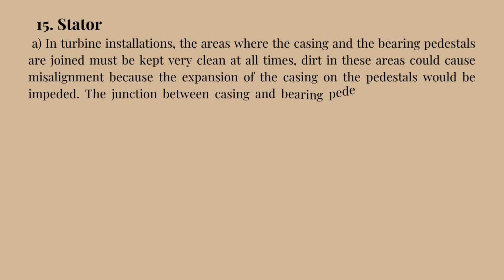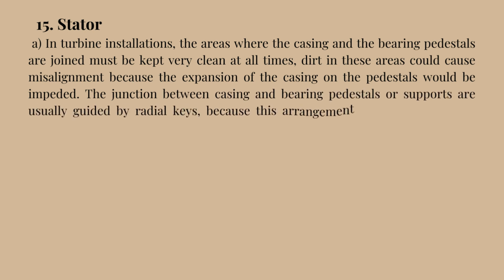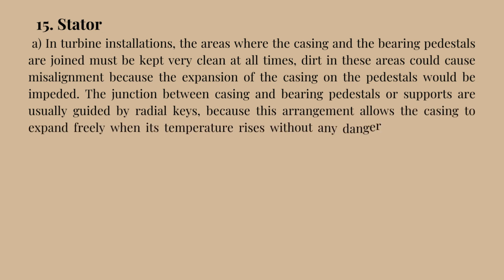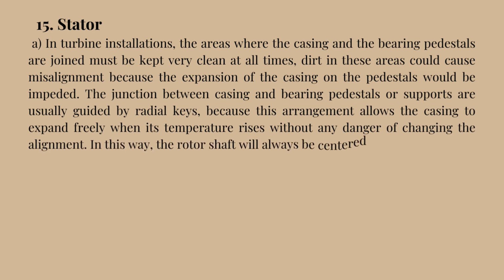The junction between casing and bearing pedestals or supports are usually guided by radial keys, because this arrangement allows the casing to expand freely when its temperature rises without any danger of changing the alignment. In this way, the rotor shaft will always be centered on the bearings.